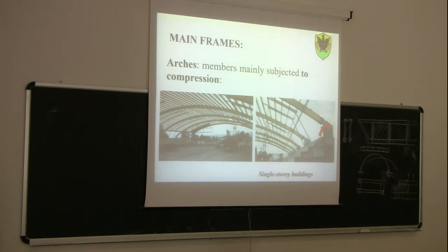Okay, now in terms of deflection, we said before that to ensure that this arch will behave as an arch, not as a curved beam, we need to make sure that the horizontal deflection here is quite small. So meaning that here the deflection must be quite small. Now, the question is, if I'm going to build the same structure made of timber, which will have the same cross section, what kind of deflection will I have here because of the arch? So this arch is basically pushing here, so I'm expecting to have a deflection. So this is like a cantilever subject to a horizontal force. If I do this structure here out of timber, I will have the same cross section. So, what kind of deflection can I expect relative to the structure made of reinforced concrete?